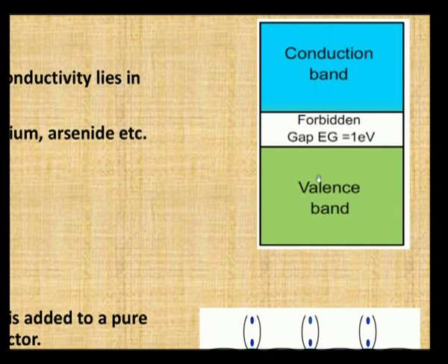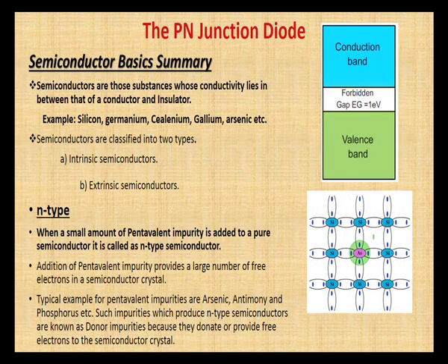So, the valence electron can easily go to the conduction band and we will get the free electrons for the current. When we come to the semiconductor, there will be a narrow forbidden gap, so we need a voltage to send the electron from the valence band to the conduction band. As in the case of an insulator, there is a wider forbidden gap. There are no free electrons for the conduction. This is the difference between insulator, conductor and a semiconductor.